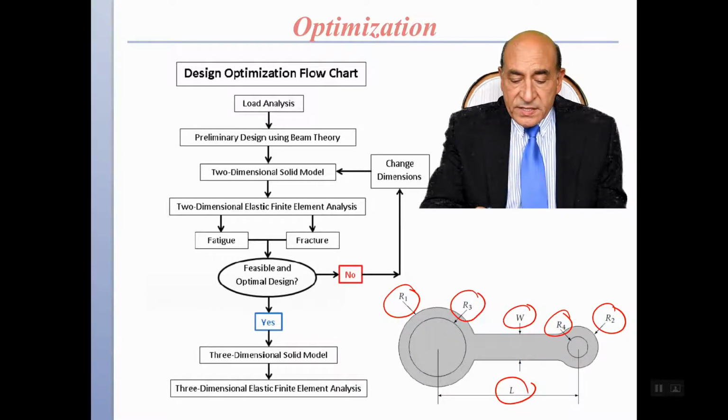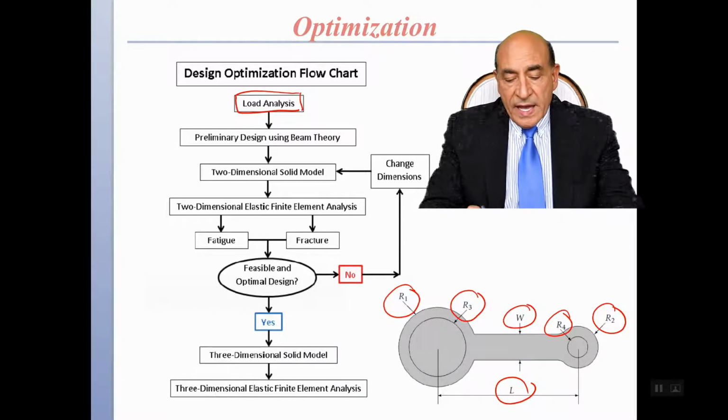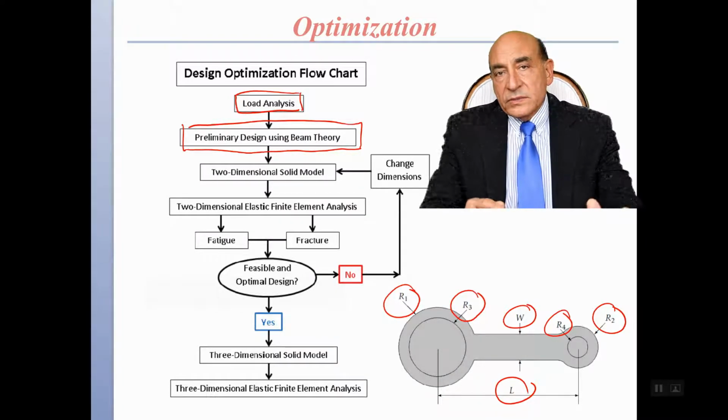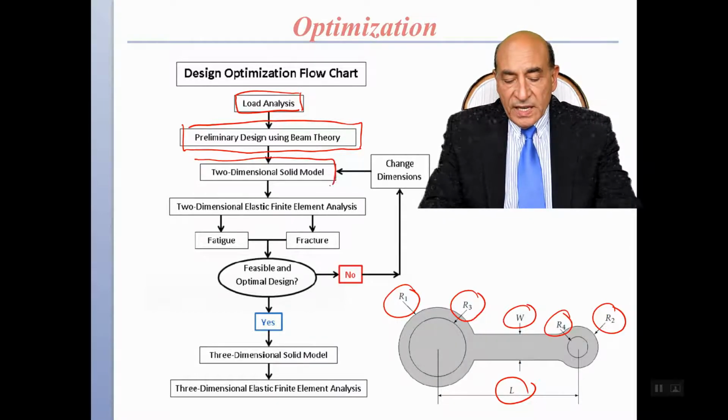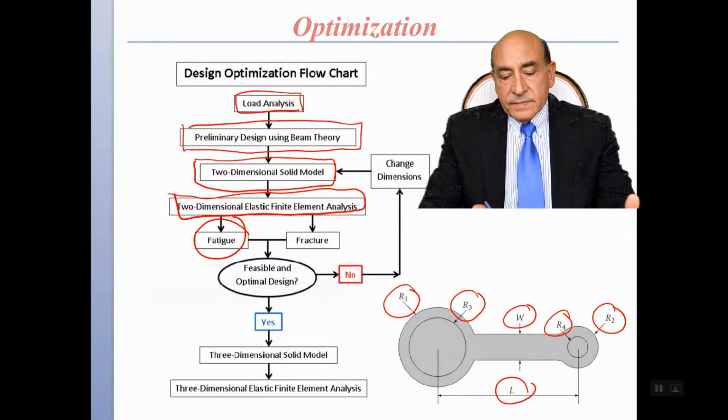So the process starts, as we mentioned, from a load analysis, and then we use beam theory to determine roughly stresses and deflections. And once we have done that, then we can establish a 2D model in COMSOL and check to see if that is done with finite element. And then once this is done with finite element, we determine lifetime based on fatigue, lifetime based on fracture.